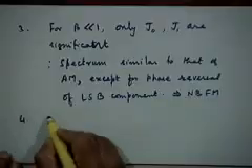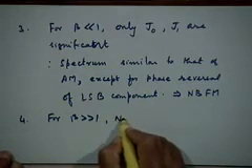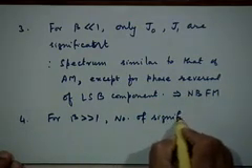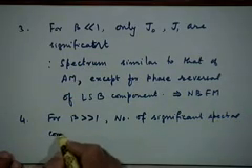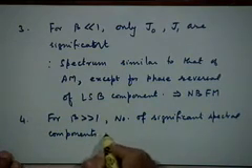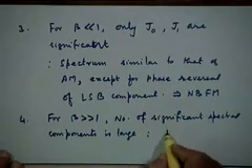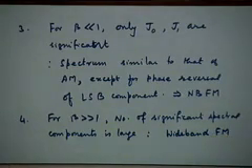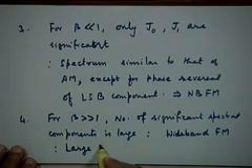As against this, when beta is very large, the number of significant spectral components is very large, and such a signal is said to be wideband FM or wideband PM. It could be narrowband PM and wideband PM, right. So this implies large bandwidth.